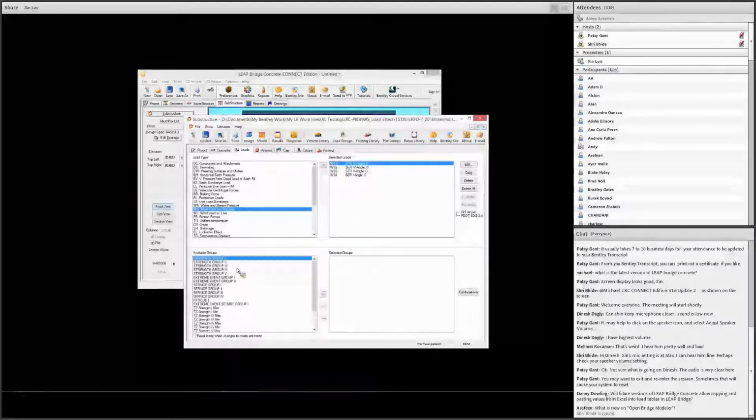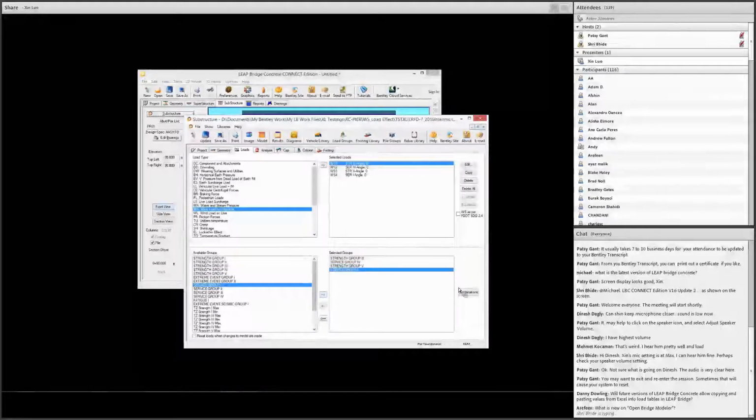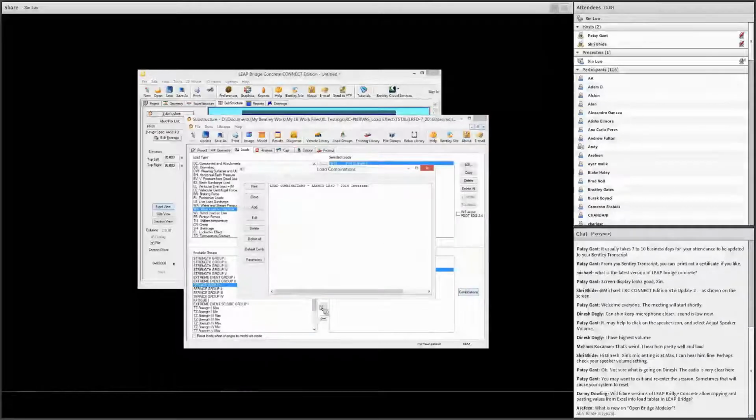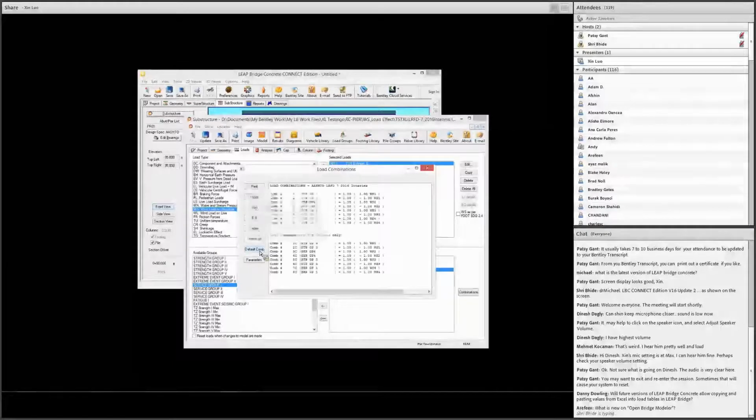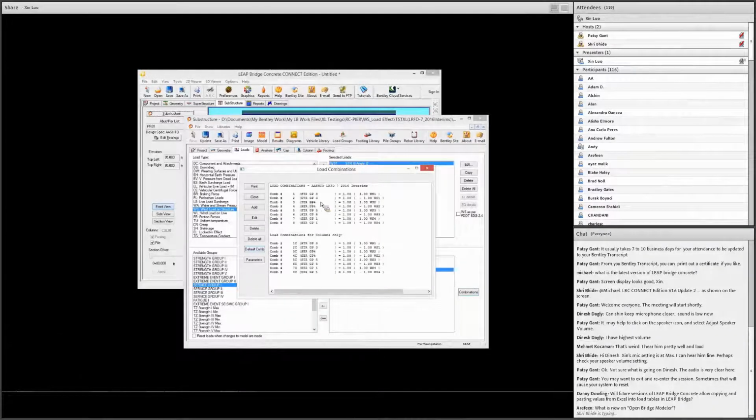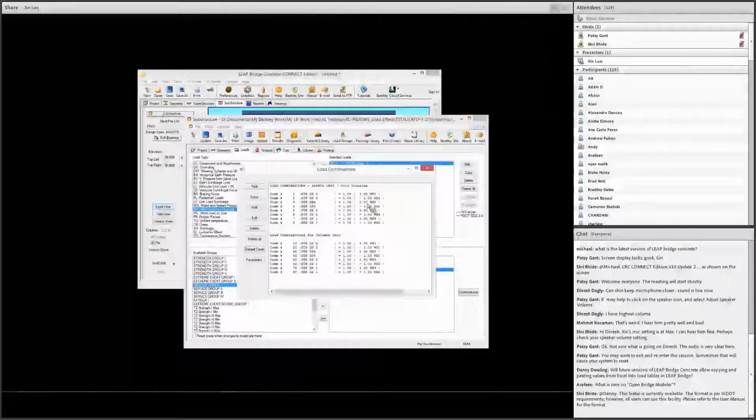Then let's do the load combination generation. So to simplify that, we choose here strength 3, service 4, strength 5, service 1. Click the load combination button. Then we can use the default combination. Then it automatically generated. In this case, I do not include any other load types, just the wind load cases. So you can clearly see which wind load case goes into which load combinations.